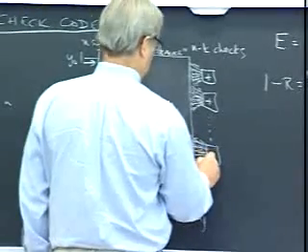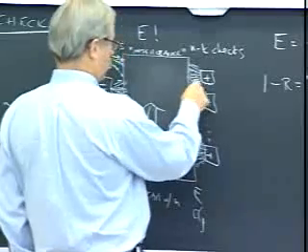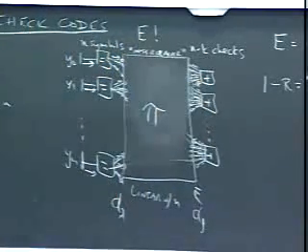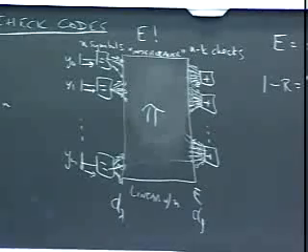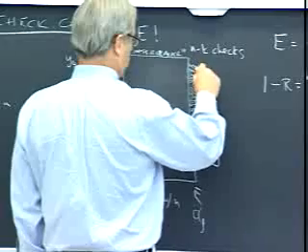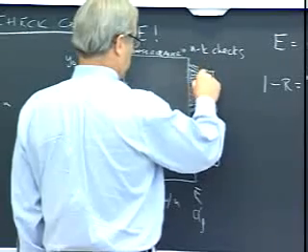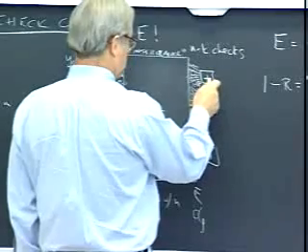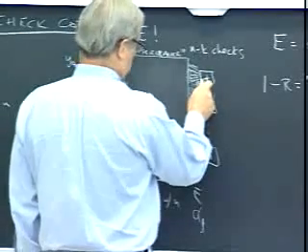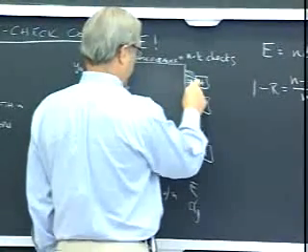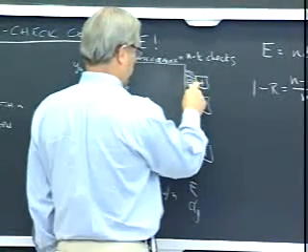Based on that, to find the outgoing message, say on this line here, what's our rule? Our rule is to take the incoming messages on all D-1 of these nodes and combine their likelihoods according to which of these is consistent with a zero output here, and which of these is consistent with a 1 going out here.